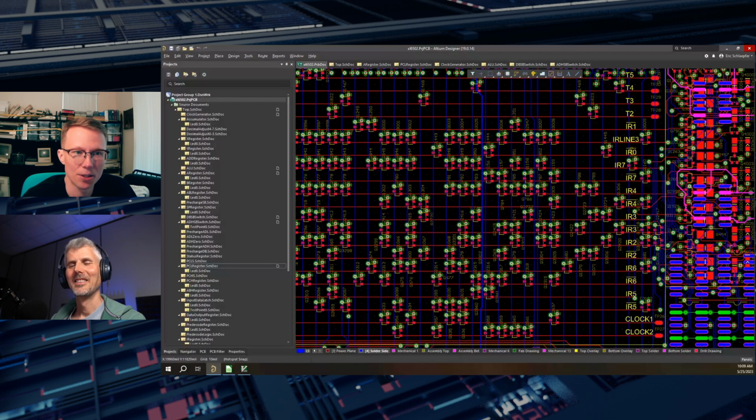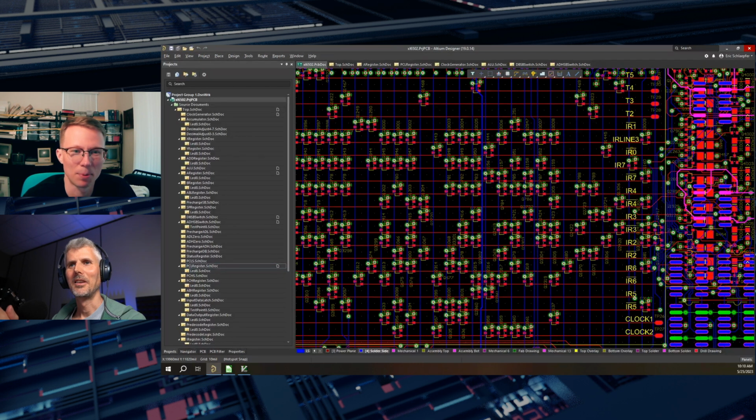Yeah, and then from there I started putting in other individual instructions. So I would feed in something like an add one to the accumulator. I don't really remember what other instructions I used, but it was a fairly abbreviated list of just a couple of instructions to see if I could get any behavior out of it. Then I would look at the instruction register LEDs, and LEDs all over the board, to try and figure out what was going on. And then at some point I also implemented the single step circuit so that I could single step the processor without having to stop the clock.